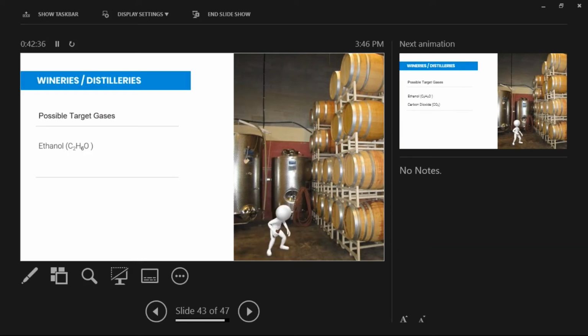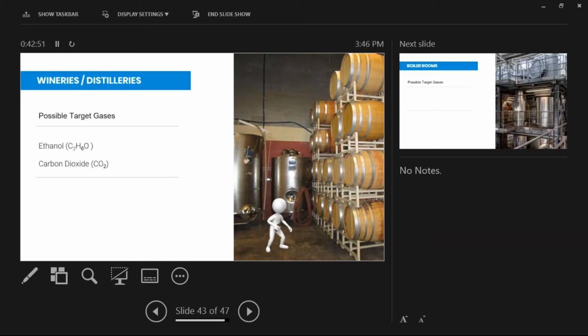And typically they'll classify that distilling room, and they'll want an explosion-proof fan and an explosion-proof sensor transmitter within that particular area of the envelope.